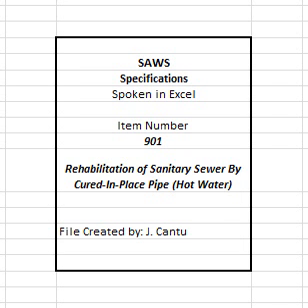901.5 Construction. 1. Installer qualification requirements. A. Installation of the CIPP products shall be performed by a workforce that is experienced and certified in installation of the products. The installer shall be certified by the CIPP product manufacturer to have been trained and approved in the installation of their CIPP products and have a minimum of 3 years total experience with the product. The contractor shall submit such certification of hot water CIPP installer to owner.